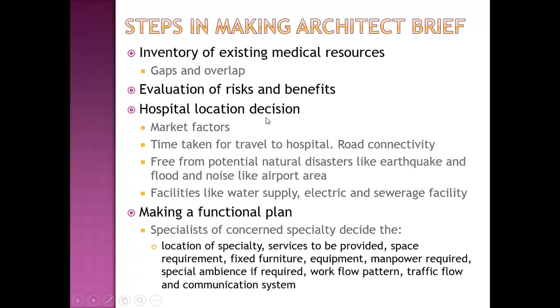Hospital location decision include market factors, time taken to travel to hospital, that is road connectivity. Location should be free from potential natural disasters like earthquake and floods, and even noises like airport area. There should be facilities like water supply, electric supply, and sewerage facility while considering hospital location decision.